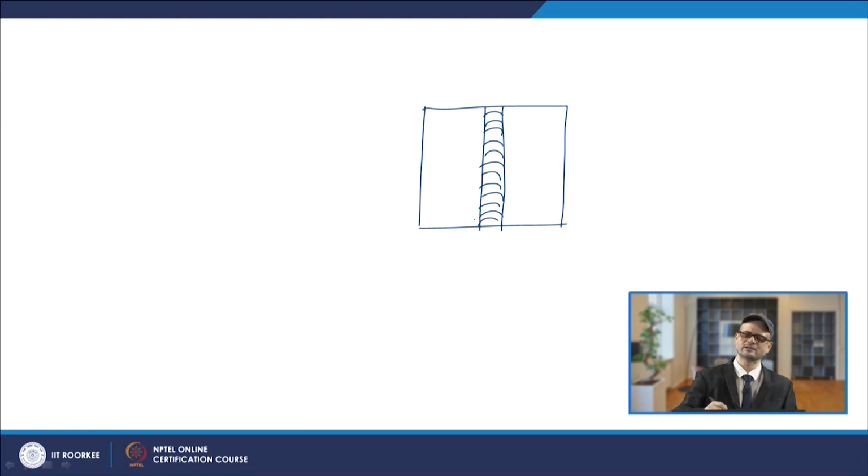Now, since the weld metal is in liquid state and it has to solidify, you have shrinkage which takes place either along the longitudinal direction or along the transverse direction. The shrinkage along the longitudinal direction is termed longitudinal shrinkage. Similarly, you will have shrinkage in the transverse direction, which is the transverse shrinkage. Then you have distortions going out of shape. You have angular distortions, which take place at some angle, with bowing or bending. This distortion is normally seen in the case of fillet welds.